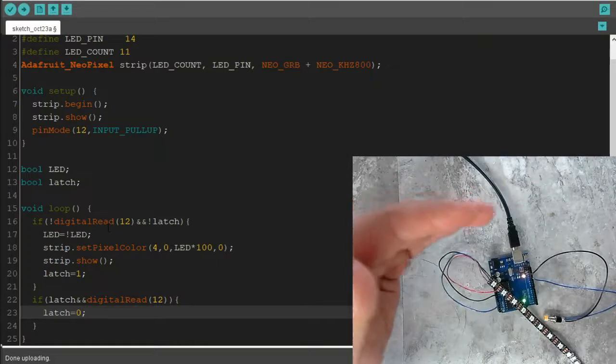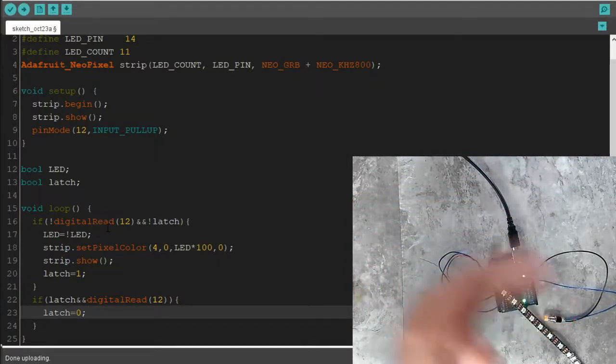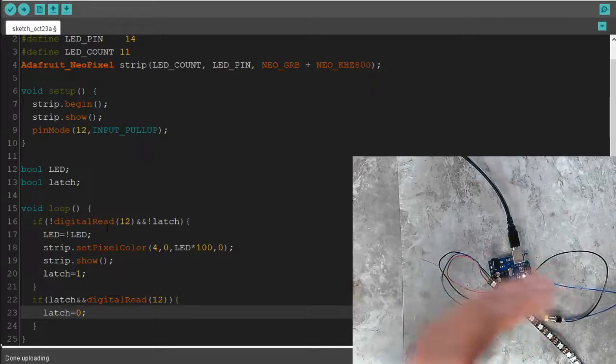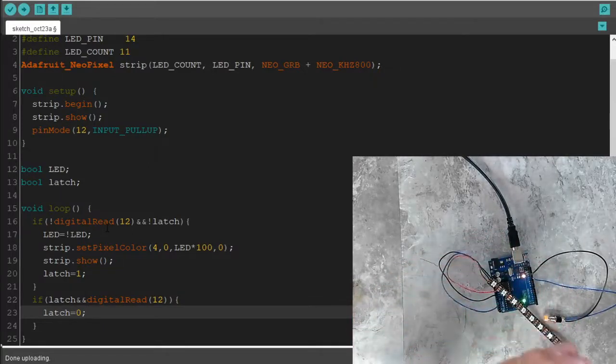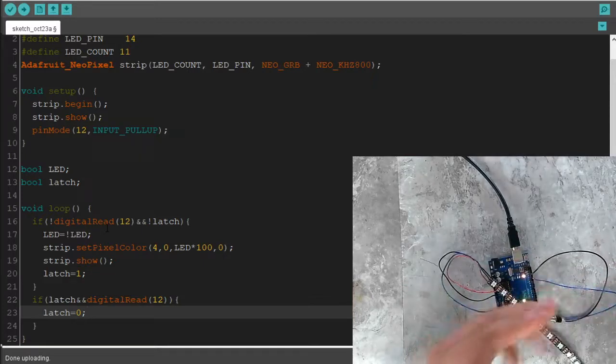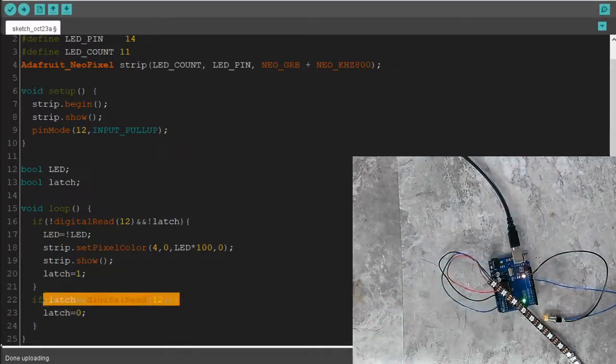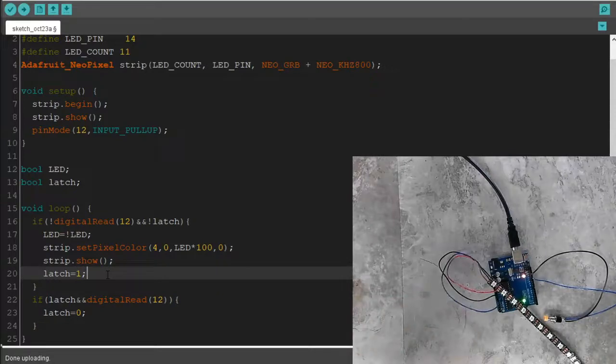It goes eventually to low, like within nanoseconds, picoseconds, it goes low. But then it sort of wanders back up a little bit and then comes low again. It's called electrical bounce. And so that wandering back up in the code here can delatch that button and then it runs it through again. So over time, like it can sway a little bit.